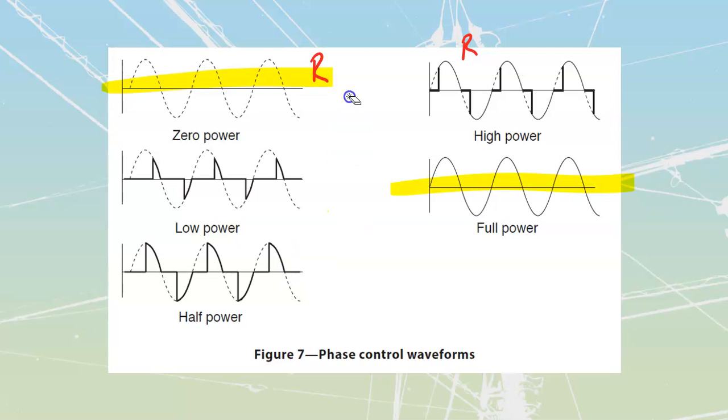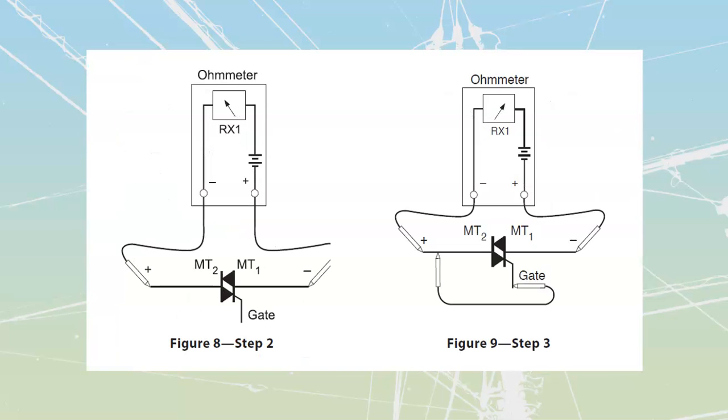If we want to get full control, we're going to have to go back to that same resistor capacitor, RC type, that we are going to run through. It just gives us a much broader range. We're just going to be trickling electrons onto that capacitor until it builds up enough voltage to give us that little kick through the gate. And when it gives a kick through the gate, it actually discharges that cap.